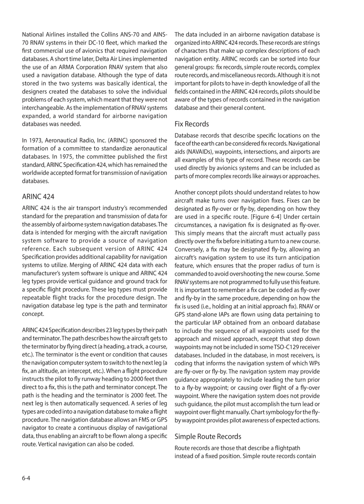Some RNAV systems are not programmed to fully use this feature. It is important to remember a fix can be coded as flyover and flyby in the same procedure, depending on how the fix is used, i.e., holding at an initial approach fix.